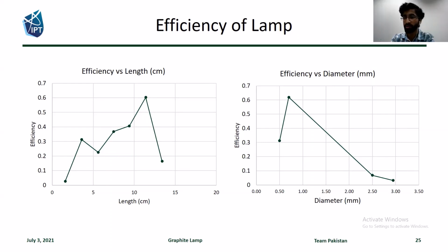Yeah, I'm going towards that part. As I mentioned, the initial settings for the input power were in voltage and amperes. So that's the input power. I have to divide output power over input power. Now the power is related to intensity times surface area. The intensity that I calculated from the lamp, I multiplied it with the surface area of the rod, the outer cylindrical surface of the rod, and for that particular rod, that gave me the output power. There is a proportionality there, and when I divided, that gave me this particular result in terms of the efficiency.